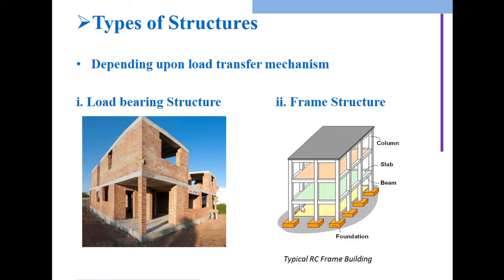Or there is already per meter cube loading given in IS code 875 part 1. IS code 875 1987 part 1. So you can multiply that particular loading with your overall length. If you want to assign it as a meter cubic load, or you can use only the per meter loading and assign it with respect to the length. Okay, so it automatically assigns.